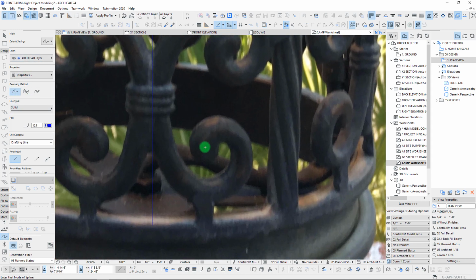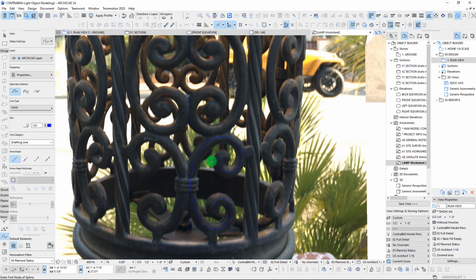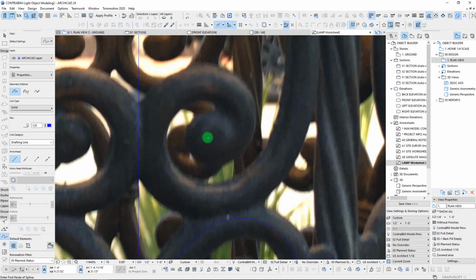But what I've found when creating these shapes is the less points we can put onto our polyline, the better off we're going to be. So we want to keep these kind of nice, and you know, if we can try to keep them to maybe like 10 points or less, then I think that's going to help us. So we're at 1, 2, 3, 4, 5, 6, 7, 8, 9, 10. And so hopefully this is going to work well for us, but you never know until you actually start to go and place elements.